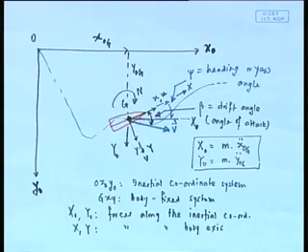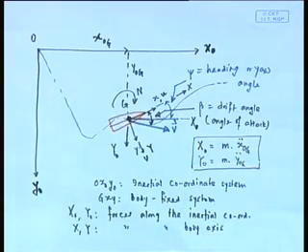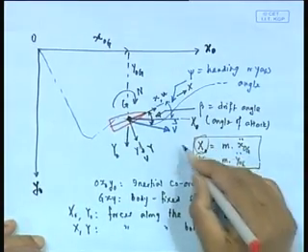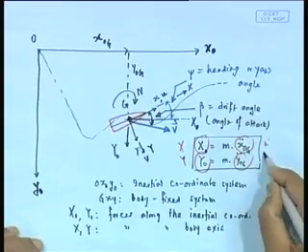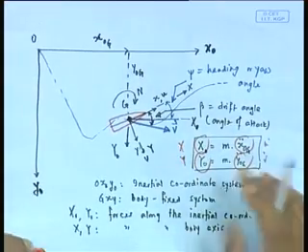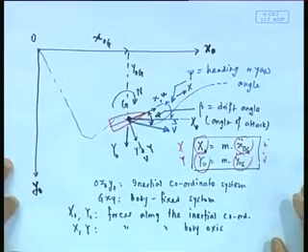So as far as hull is concerned, you always want to know what is the force coming on the hull along its x axis and along its y axis, and that is another reason why I have to rewrite them in terms of x, y and in terms of u, v. That means I need to rewrite this by changing this x0, y0 to x and y and changing this to u dot and v dot. We have to do that. We will be doing it eventually, but we will have to do that by using coordinate transformation.